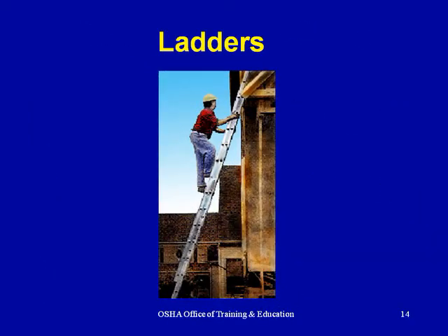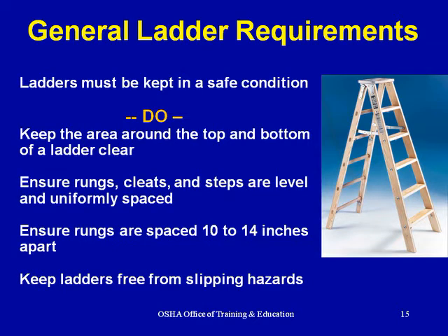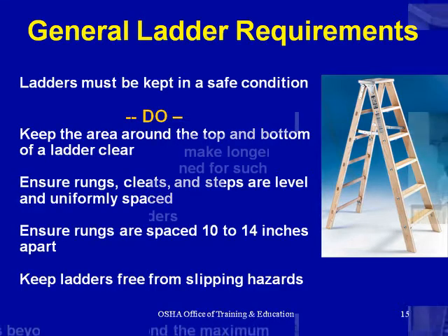Slide 14, ladders. General ladder requirements. Ladders must be kept in a safe condition. Do keep the area around the top and bottom of a ladder clear. Ensure rungs, cleats, and steps are level and uniformly spaced. Ensure rungs are spaced 10 to 14 inches apart. Keep ladders free from slipping hazards.